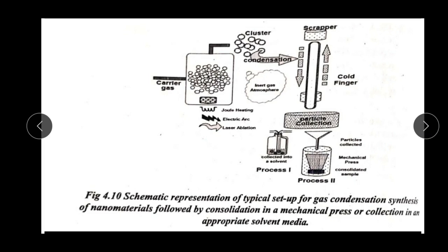Now coming to the gas condensation process. The next method to synthesize nanopowder particles, dear students, is gas condensation processing. As you can see in the image, this is the schematic representation of a typical setup of gas condensation synthesis of nanoparticles, followed by consolidation in a mechanical press, or collection in an appropriate solvent media.